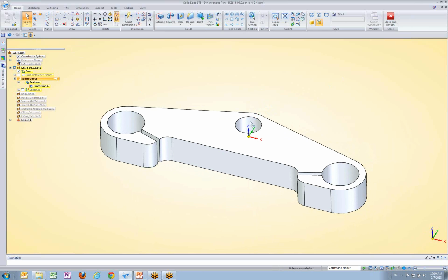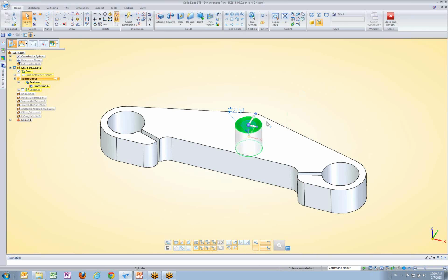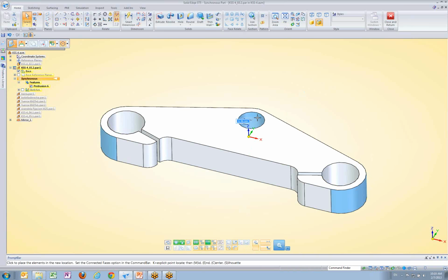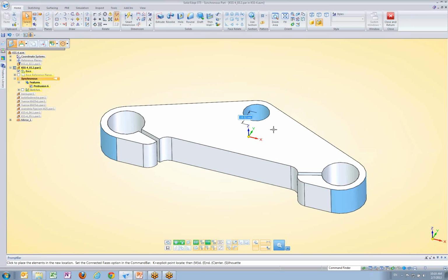And as an example of that, I'm just going to reach in and grab this cutout in the middle here. And you'll notice live rules comes up. Again, we're not going into much depth of live rules. The only thing I'll tell you to do right now is turn off this lock to base reference plane. That just prevents features that are centered on that origin you see from moving. And in this case, just for demonstrative purposes, I want to click on that arrow and just start that move. And you can see that as I adjust my part, synchronous technology is maintaining that design intent. It's maintaining the tangency of those edges, the constant radii.